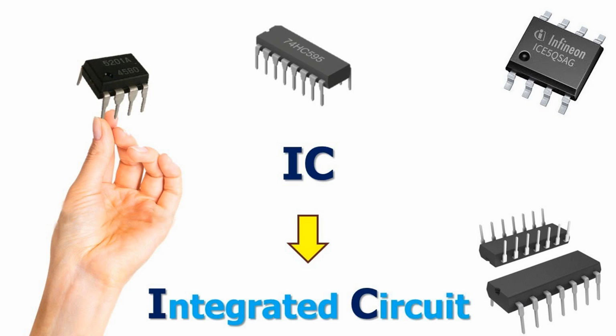Types of shift registers. There are various types of shift registers, including serial in, serial out, SISO, shift registers. Serial in, parallel out, SIPO, shift registers. Parallel in, serial out, PISO, shift registers. Parallel in, parallel out, PIPO, shift registers. Applications. Shift register ICs are used in applications like data storage, data serialization, parallel to serial and serial to parallel conversion, data transfer between different clock domains, LED displays, and delay circuits.